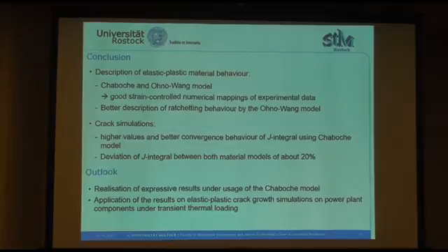In the future, I want to realize expressive results under the usage of the Chaboche model because its computational time is a lot shorter than under the usage of the Numerical model. Moreover, I want to apply the results to elastic-plastic crack growth simulations on power plant components under transient thermal loading, and because of that it is necessary to use temperature-dependent material parameters, and this option is already implemented in Abaqus for the Chaboche model.